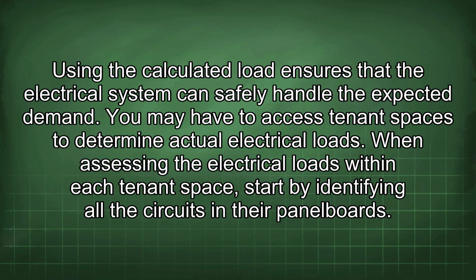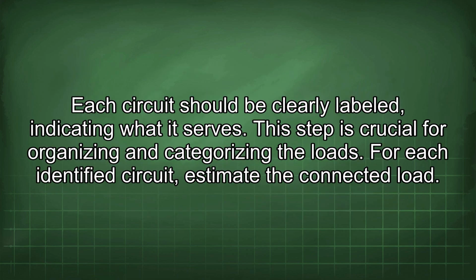When assessing the electrical loads within each tenant space, start by identifying all the circuits and their panelboards. Each circuit should be clearly labeled, indicating what it serves. This step is crucial for organizing and categorizing the loads.